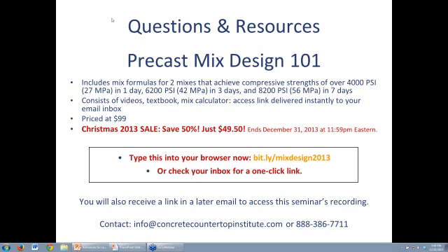I don't currently use pozzolans. Do the properties help minimize curling during the curing process? Yes. Or could it be the combination of water reducer and the accelerator I use? Don't know. It's too hard to describe and diagnose from just a general statement. You're probably not using enough water reducer and probably using too much water. So curling is generally caused by differential drying where one side dries faster than the other, and that's largely driven by water content in the concrete and permeability or porosity of the concrete as it's drying out. So there's many, many different factors that could be leading to that.